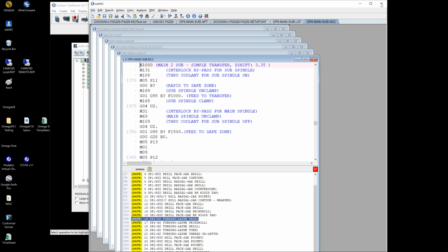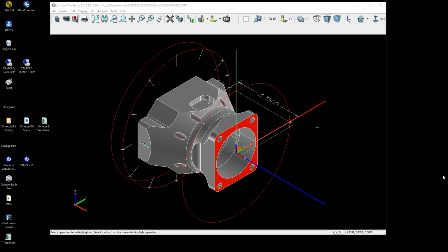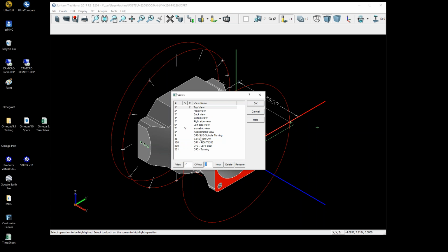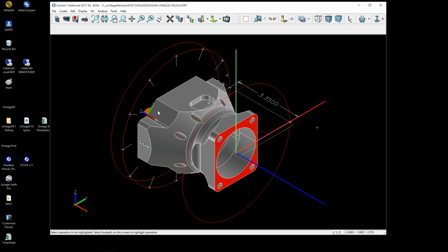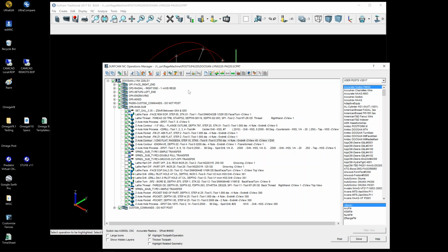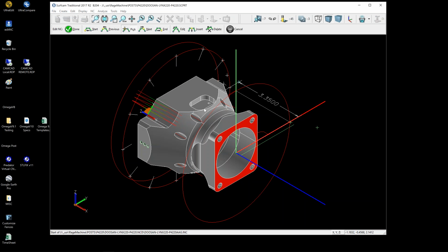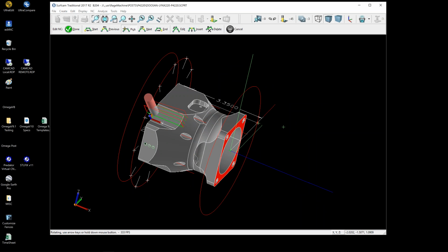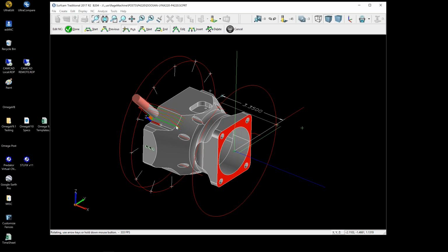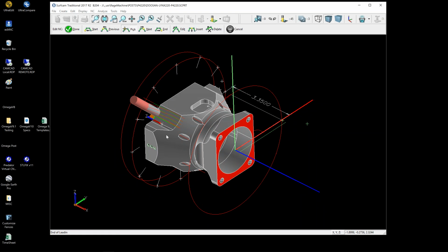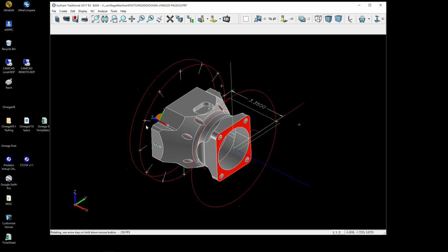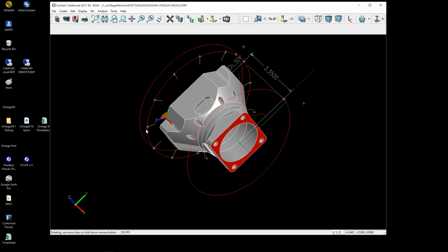So anyway, using this technique, this allows us the freedom to use and place a C view anywhere on the part that's near a particular feature in order to do some programming there and have the feature relative to it. Again, everything gets converted into a global coordinate system when the file is presented to the post processor. So it really doesn't matter where the origin of our C view lives. And in this case, I've got it on the corner of this flat face here at 45 degrees.